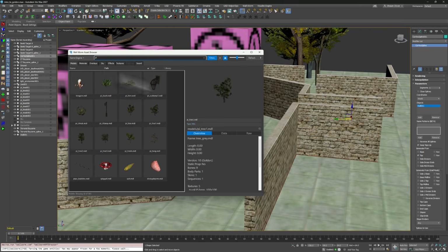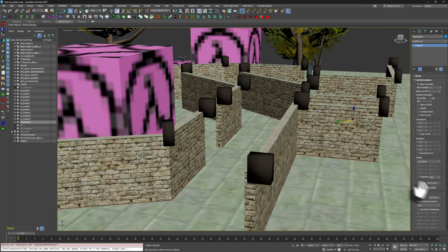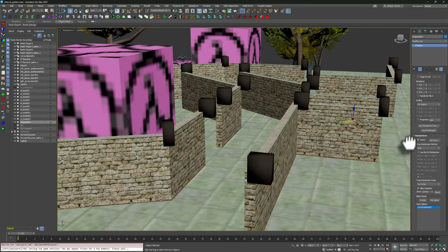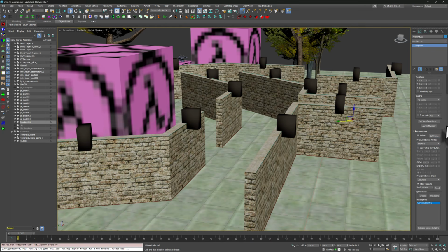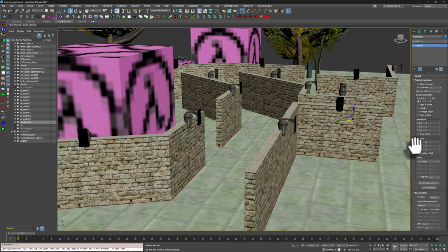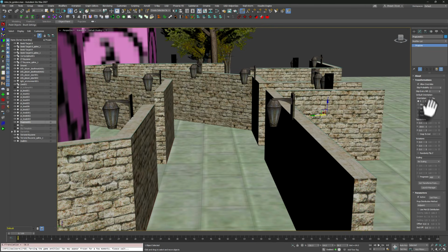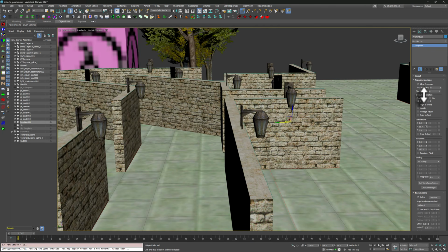Open the Model tab of the Asset Browser, find a light model, right-click it, and click the Create Prop Line button. Now the model is distributed along the wall at the corners. Changing the prop distribution method to midpoint will move them from the knots to the segment midpoints. To see the meshes, go to the Performance and Display rollout and change the Source Model Display mode to Lowest LOD. And in the Transformation rollout, we can move and rotate the models to make them align to the walls.